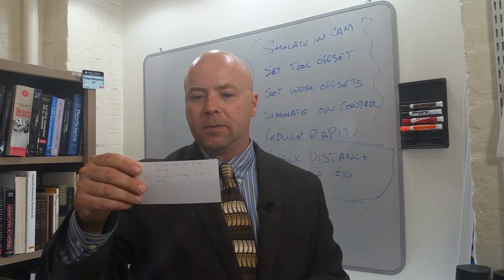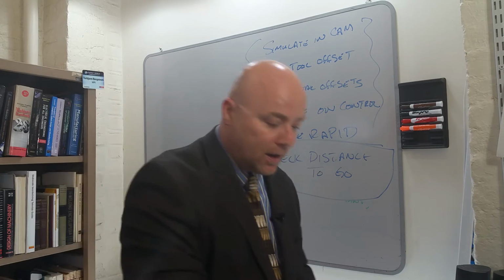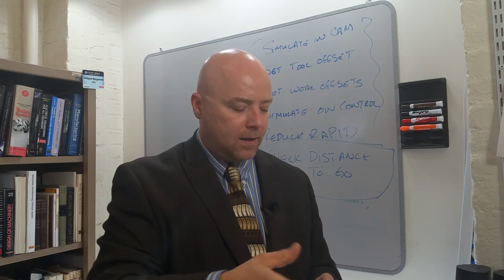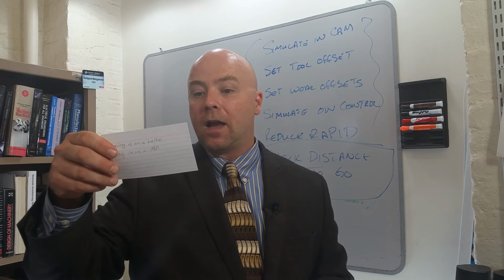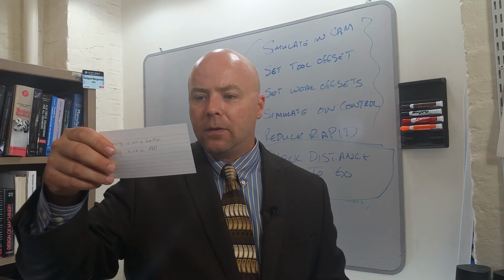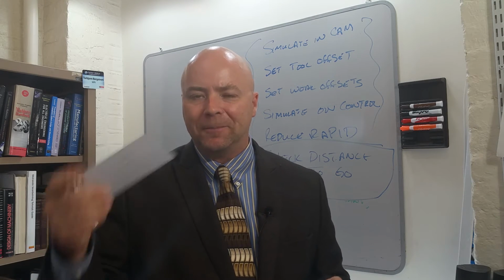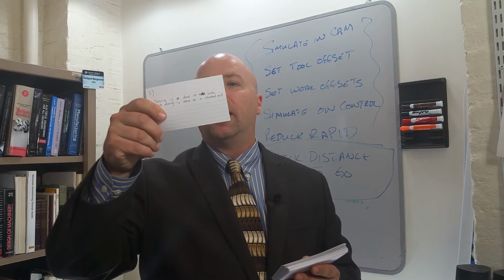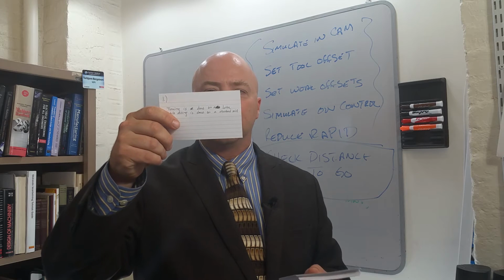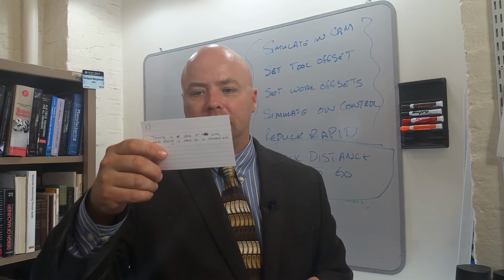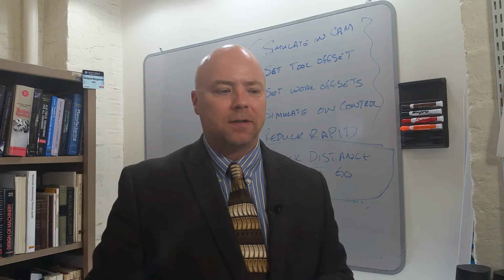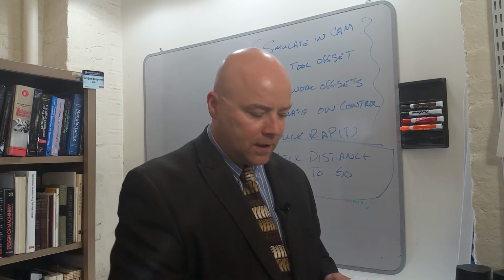Stopping the tool before it hits the material and checking the distance to go. I got 1 correct. Having the PLA sign off and check the work. Yeah, not necessarily. Stopping to check. It won't go through the thing. I think they mean check the distance to go. Distance to go. Simulating tool paths is most important because it can prevent some of the errors. I still vote for check distance to go as being the most important, but at least you knew what the safety steps were.